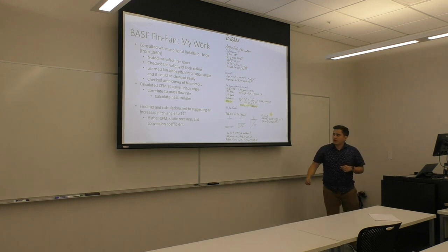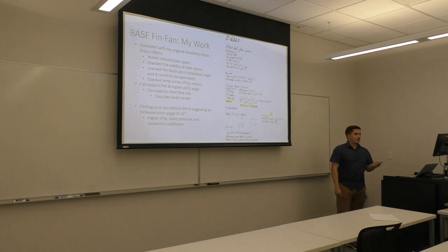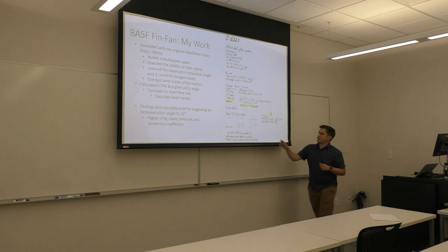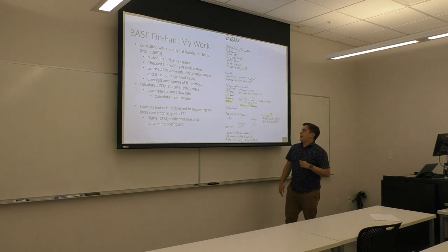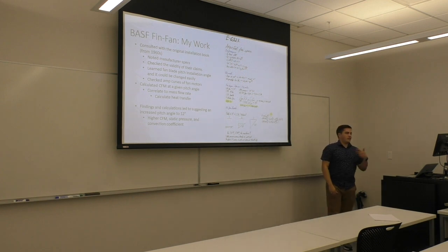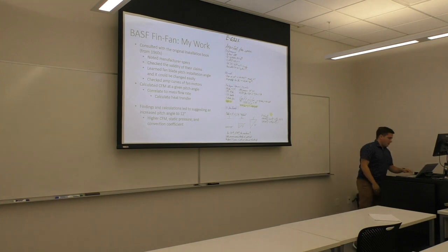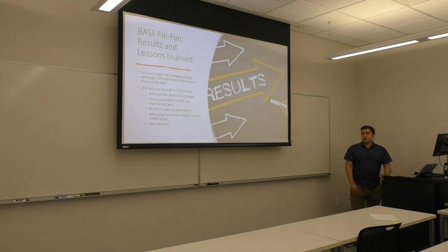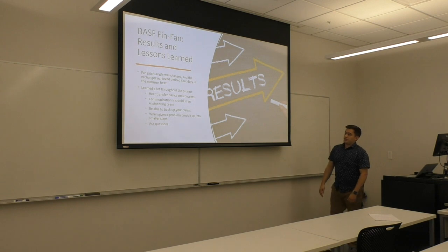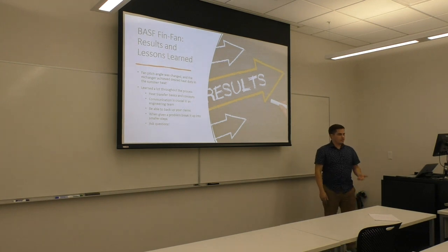I believe. And so I was able to figure out how to calculate the different CFMs that you would get at different pitch angles with this equation specifically right here, and convert that into a mass flow rate, and then figure out the amount of heat that you get out of it. After doing all that, I was able to make the right recommendations. So we went from about 2.9 degrees to 12 degrees. You didn't need much, but